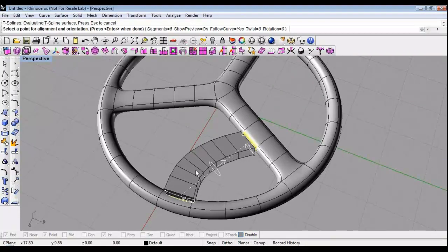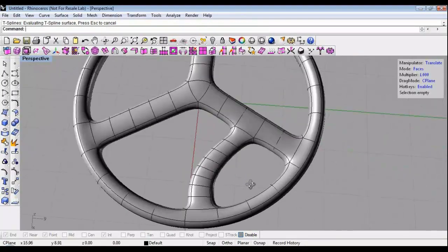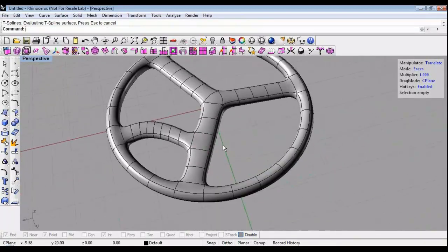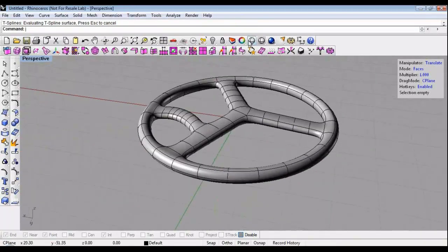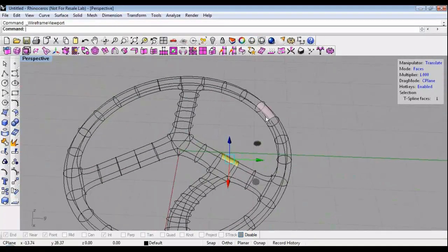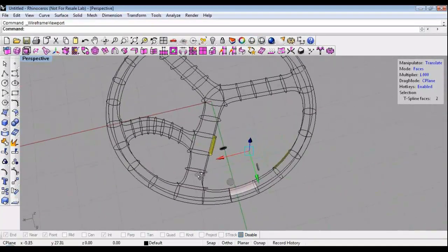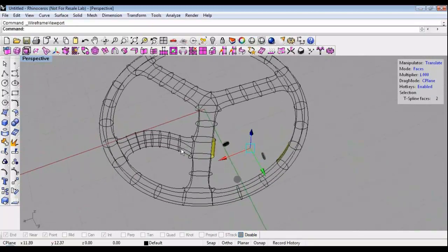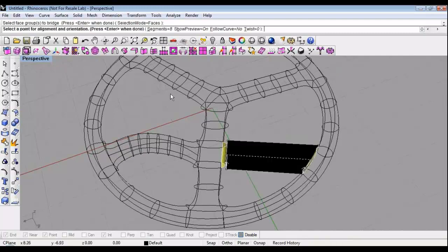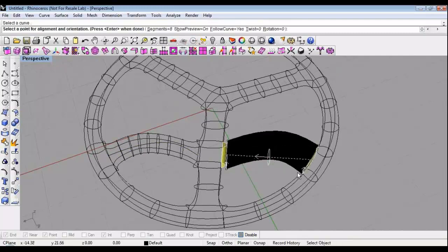And then it will go ahead and apply the bridge like that. If I want that same bridge to be over here, then I can use that same curve. I don't need to move it. I'll just click the faces where I want the bridge to go, do the bridge command again, and say follow curve, just click this curve and it will move that curve over here.